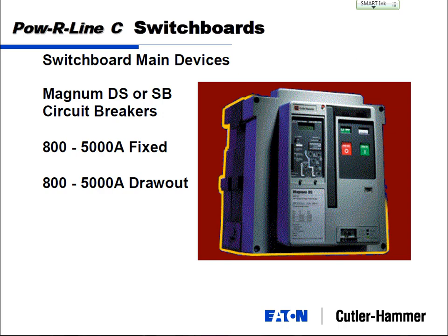Generally speaking, electrical equipment, although nobody will actually publish an expiration date, generally you want to look at about 30 years before your equipment is ready to be replaced. Anything extra is usually borrowed time. Sometimes 35 is good. Other times you get a dirty environment or an outdoor location where it's hot, something dusty, or something where you're running a lot of current through it at all times. Maybe you only get 20, 25 years of life out of that equipment. So maintenance is one of the good benefits of these breakers.